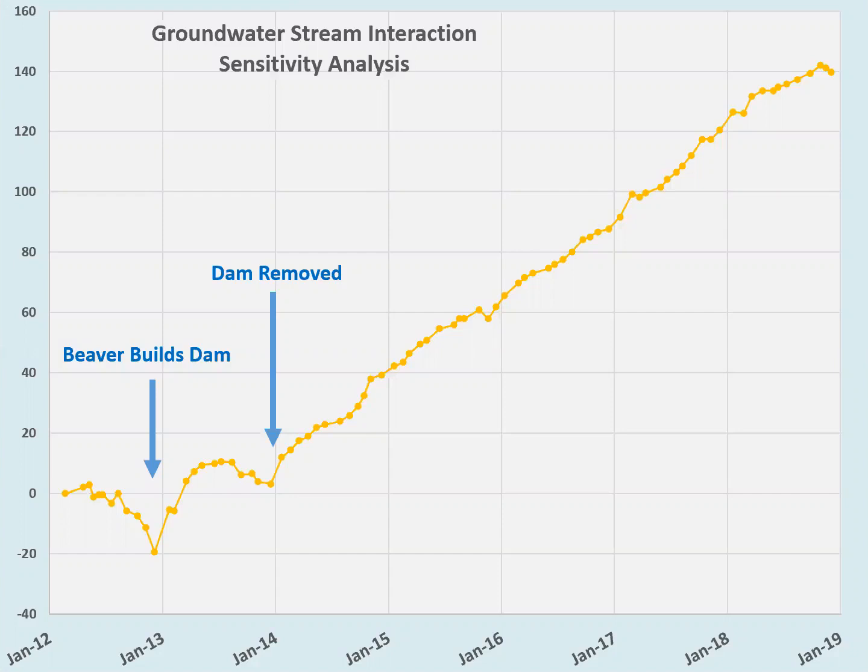There had been some studies in the past in that very area. We all knew that there was a seep that came into the bottom of the stream in that area that they measured. They could just take a bottle and stick it down into the bottom of the creek and capture water popping out of the stream bed and sample it or run it to the lab and analyze it.